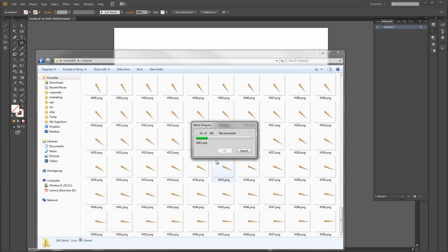And then Fireworks goes off and it takes all 360 files, takes the 24-bit PNGs and reformats them as smaller 8-bit PNGs. You're going to lose a little color, of course, because 8-bit color has a little bit less depth, but for a needle it should be plenty fine, unless you have a lot of gradients and it's a larger needle where you can see it. You might want to try it both ways. Give the engineer both the full 24-bit color set as well as the 8-bit per pixel color set.